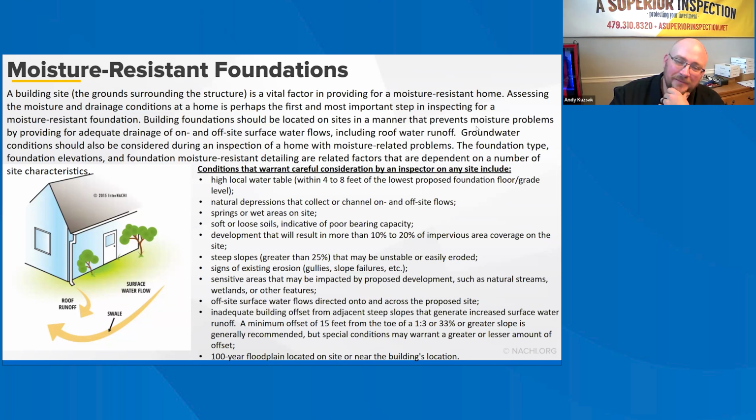And that's why in the diagram, it states that you would cut the WRB, which would be the house wrap, in an X fashion. You would wrap it on the top, wrap it on the sides, wrap it on the bottom. And while that is still recommended, that might not be required by the window manufacturer.